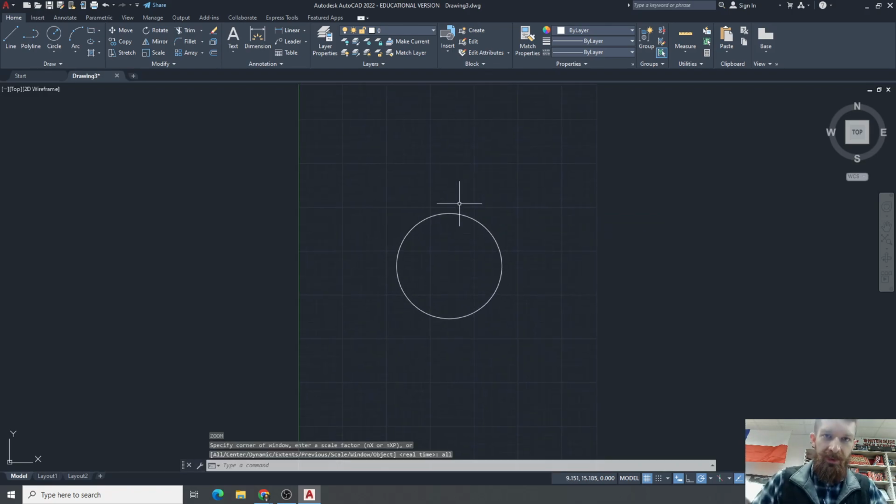But when I go to print it out, if I print it on a regular size sheet of paper, or 8.5 by 11, then I'm going to have a DSF that is something other than 1, right? So if my workspace is twice the size of the piece of paper that I'm printing on, then my scale factor is 2. Hopefully that makes sense. If I work on a limits size of 44 by 34, and then I print on a regular piece of paper, my scale factor is 4. If you need some more clarification on that, let me know. We can work on it in class together. I don't want to spend too much time on it during the video.